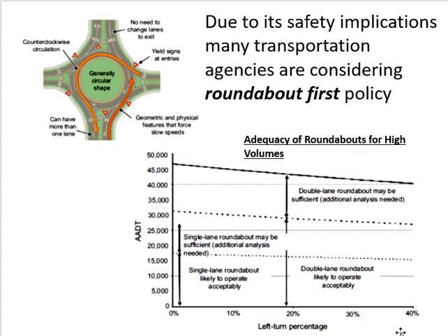But a point here is that obviously with more volume I need more lanes. So you can see here more volume, double lane. But what is happening here? The volume is less, but I'm still going for double lane because of the left turning. More left turning means more people will be going through the roundabout, so they will not take the first or the second exit.